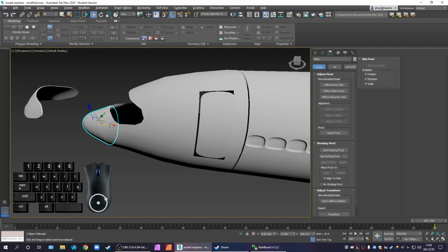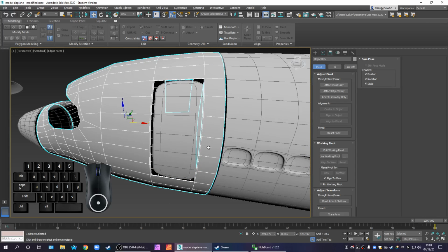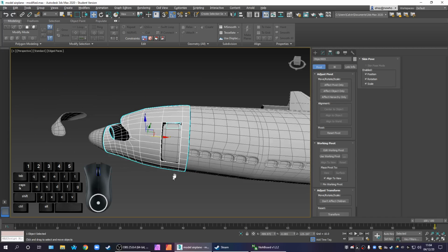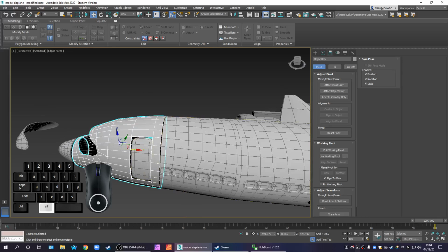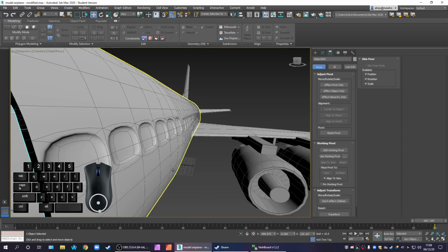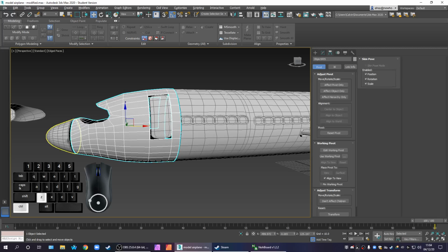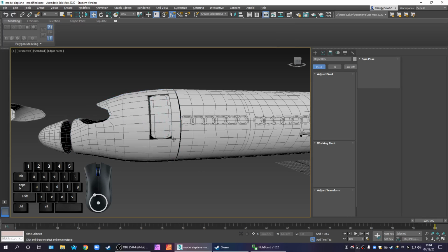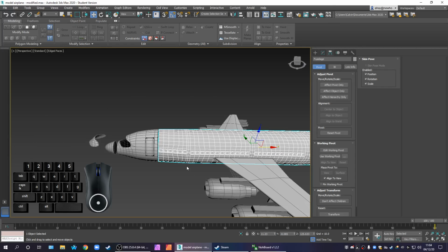So I'm doing some of my slicing now, which there's 3D printing software for doing that, but partly because it's so connected with the flow of the geometry in Max at this high detail level, and also because then I can control the thicknesses of my shell and avoid duplicating unwanted details on the inside, like the windows and things like that. That's why, finally, I'm doing some of the things that you would want to do for printing. I said these videos would be like a guide to setting up your model for print. So it is now.